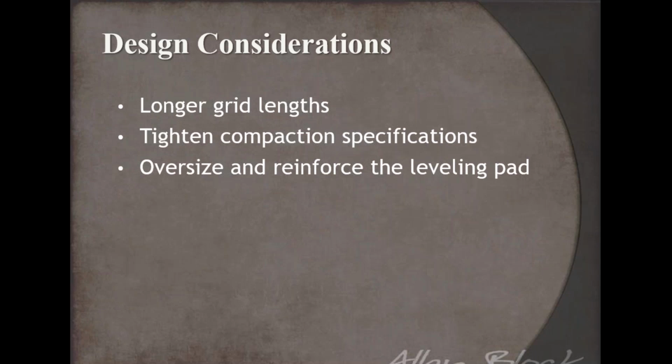And then obviously, we can't build on junk. So if you're excavating and you see some soft soils, taking a page out of remove and replace is to oversize your footing. Dig it a little deeper, dig it a little wider, even introduce some geogrid reinforcement to help you bridge over some of that questionable soil and even minimize some differential settlement. So design considerations are water management, what the reinforcement requirements are, and then making sure you've got suitable material below the wall and tightening up those compactions.